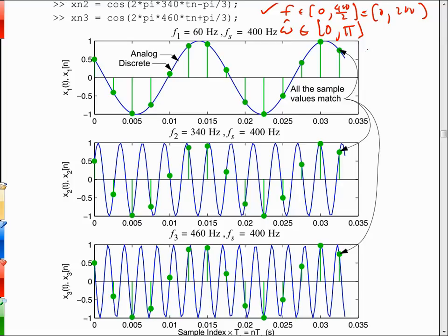What does 60 hertz become in the omega hat axis? We went through this before, but it'd be 60 over 400 times 2 pi is the omega hat. And that was, let's see, scratching out these guys, 2 goes away, and that becomes a 20. So that's 6 over 20, or is it 3 over 10 times pi? I did that right? Yeah. So that works too, right? So that is the principal alias.